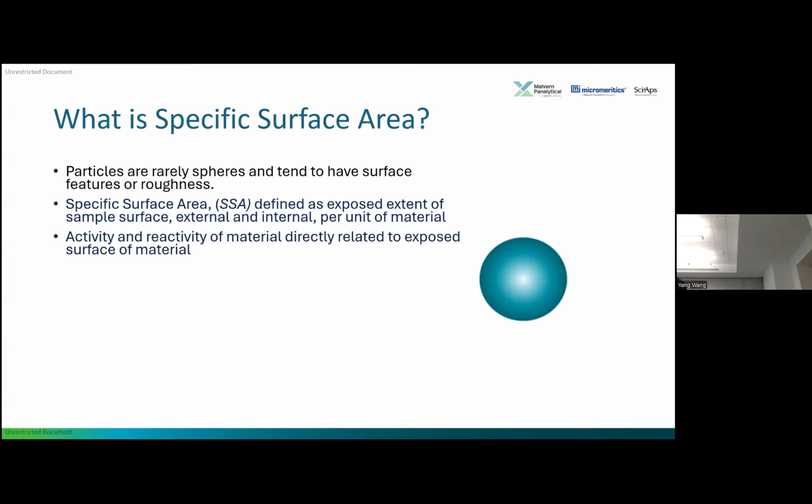It will affect activity and reactivity, because if you're trying to have some kind of reaction, it's going to happen on the surface. So if you have a big particle that's thick, the reaction is going to happen on the surface. If you have porosity, you have more surface area, and with more surface area, you can have more of the reaction occurring. Likewise, if you have smaller particle sizes and porosity, you have even more surface area. There are some materials that have really extreme surface area values, and it's a good way to measure how much reactivity you're going to get out of the material.